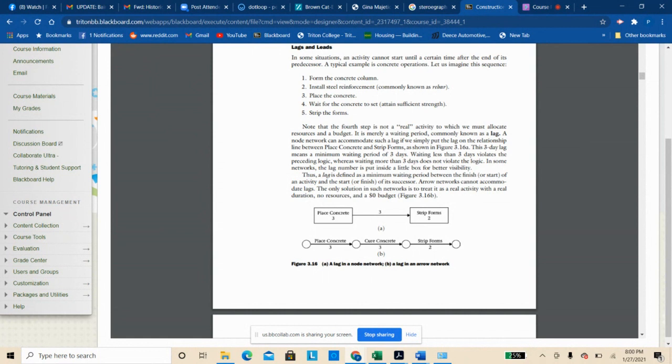So just to reiterate that, it's not just tasks you have to worry about. It's material components and their characteristics. All that kind of stuff can get into your schedule. You want to make sure you don't schedule something and not take into account those kind of characteristics. And that's why you create something like a dummy task of curing.